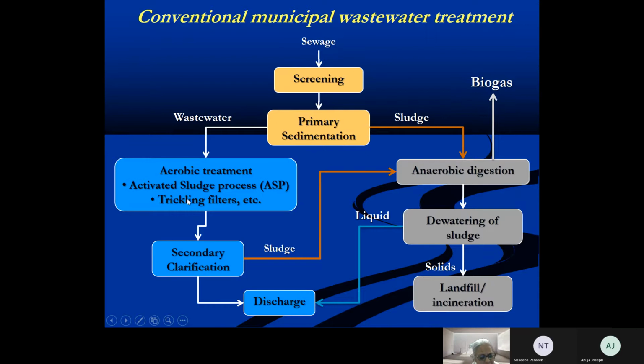Now, this wastewater has a huge amount of organic matter. Where is this organic matter coming from? It's basically fecal matter and other body fluids, basically waste excreta, mainly from human beings, but it can also include animal waste as well. So all this is very high in BOD. The BOD levels of wastewater after these discrete particles have been removed is very high. So that is taken for aerobic treatment.